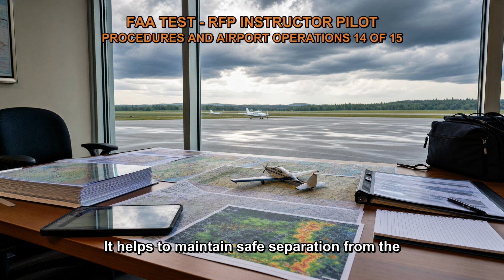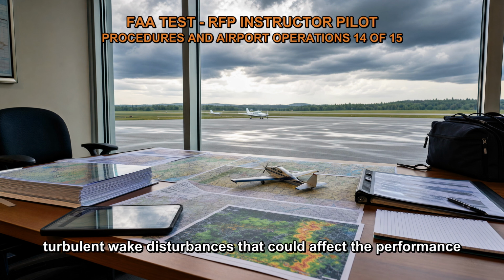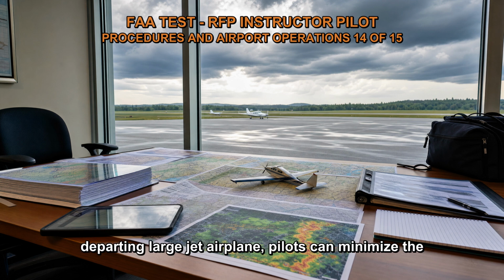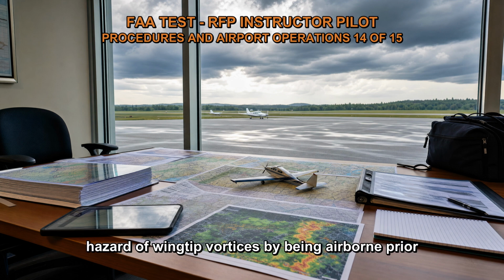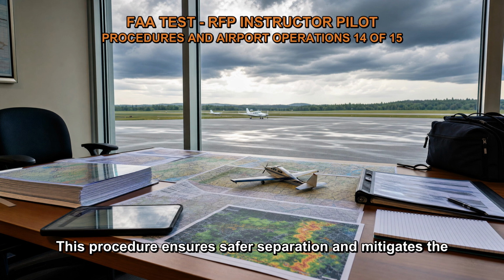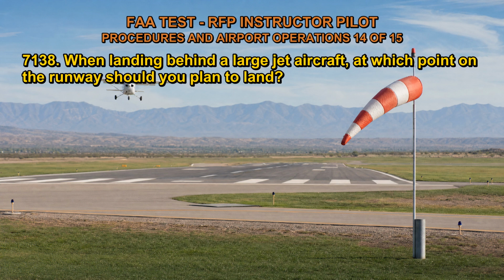It helps to maintain safe separation from the departing aircraft and reduces the risk of encountering turbulent wake disturbances that could affect the performance and stability of the following aircraft. To summarize, during a takeoff made behind a departing large jet airplane, pilots can minimize the hazard of wingtip vortices by being airborne prior to reaching the jet's flight path until able to turn clear of its wake. This procedure ensures safer separation and mitigates the potential effects of the departing aircraft's wake turbulence on the following aircraft.